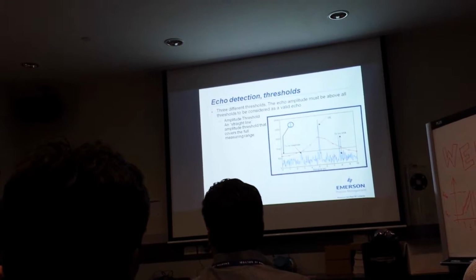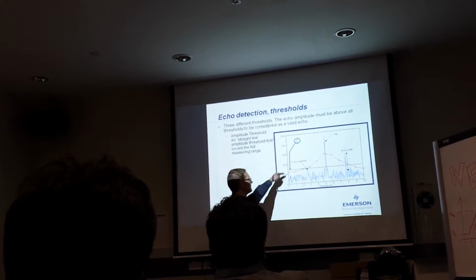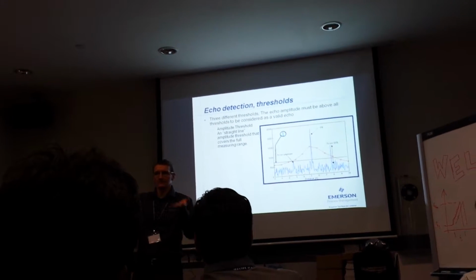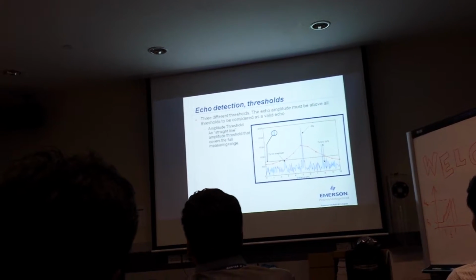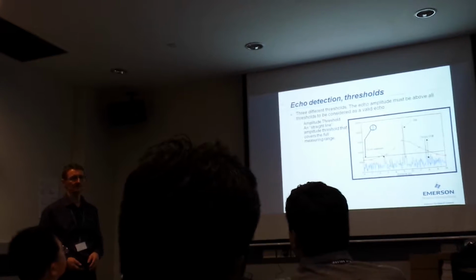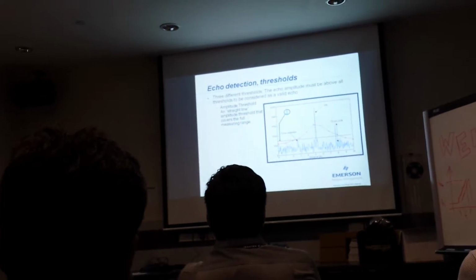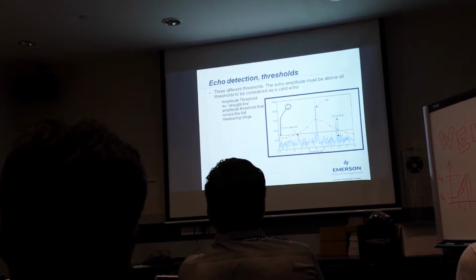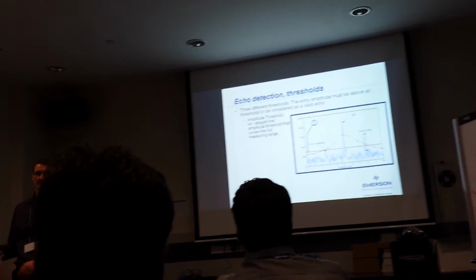This one you can change. If you feel this threshold was maybe too low and you have some noise, you can lift up the threshold because you see the peak is very good. We can increase the threshold this way, eliminating the bad peaks. So it means that all signals must be higher than this black line. Everything which is below here is thrown out, not valid, not accepted.